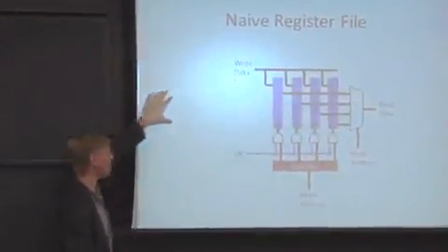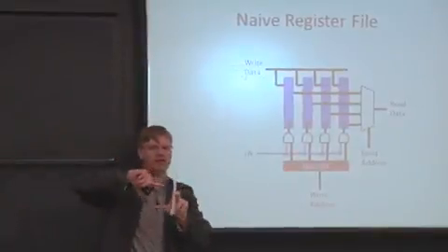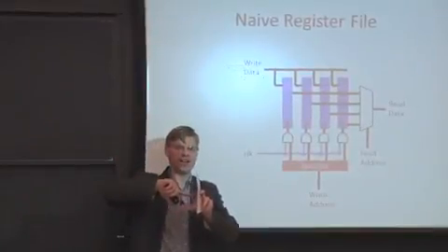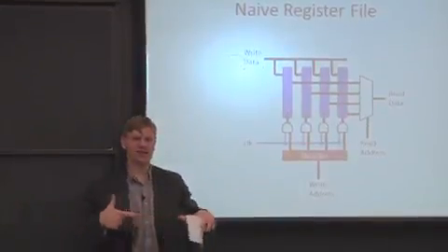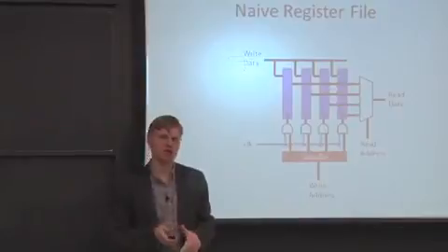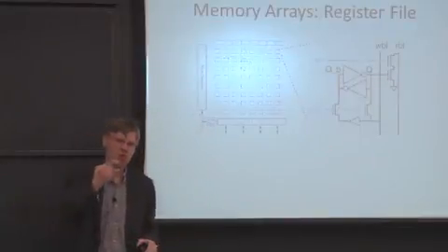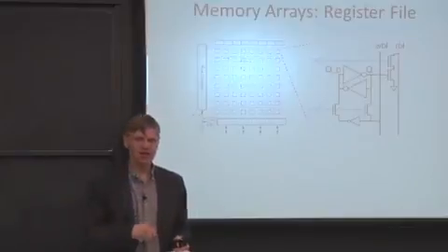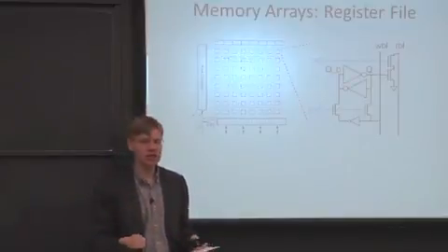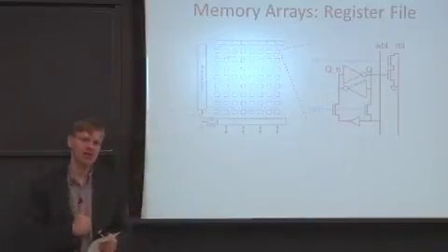And if you stack these all up, 1,000 long, your aspect ratio, your x versus y, or the size when you go to lay it down on a piece of silicon, is very long and very narrow. So you'll end up, let's say, with 1,000 bits, 1 bit tall. And that does not lay out very well, and it's not necessarily good for speed or from an area perspective. So why is it not good for speed?